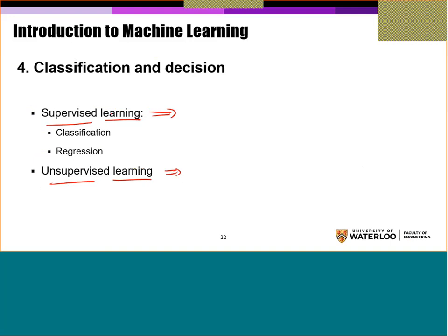What does this mean? Let me assume that I am measuring a phenomenon using an RF antenna. Let me just give a simple example. I'm measuring from an insulator, measuring two things: discharge from the insulator and discharge from the hardware. I will call this one PD, and this one corona. So I'm getting signals here.